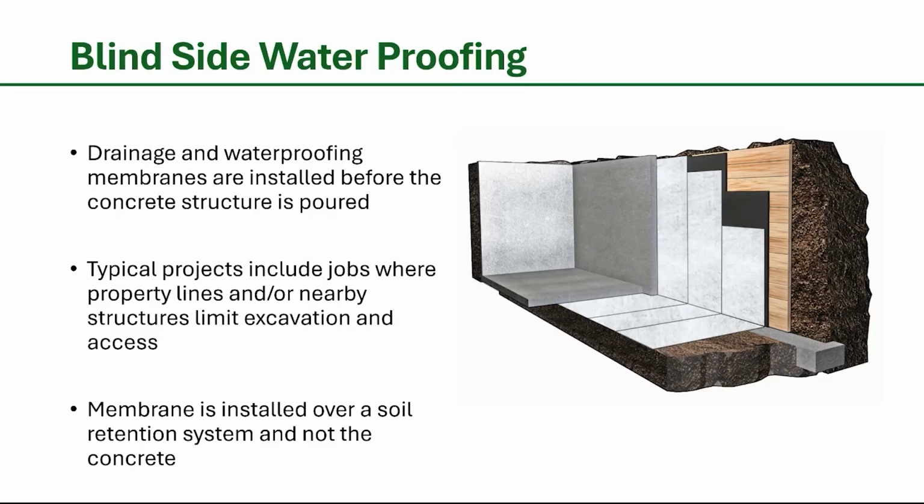It's installed in reverse. It's important that the shingle laps also be in reverse so that they are lapping out on the wet side. It's important that it's detailed correctly. Most of these membranes have a fleece backing that mechanically adheres to concrete. Some of them have an adhesive material that activates by the concrete as it hydrates. And some manufacturers couldn't decide which one to do, so they said, do both. But you'll see it. It's an excellent way to waterproof a building where you have difficulty excavating. It's also an excellent choice if you are putting an elevator pit in a historic building that didn't have one before, or putting an elevator pit in where it wasn't before. It can minimize your excavation and your slab cuts.